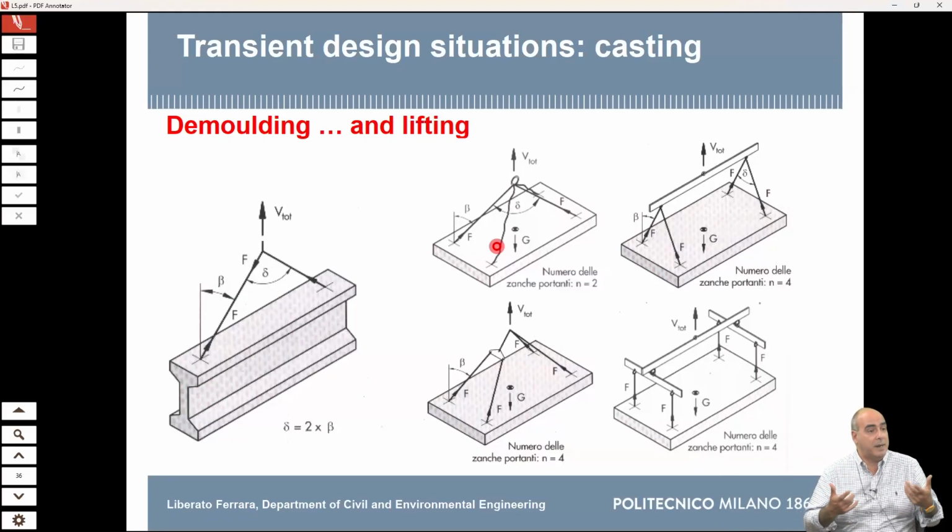But you might have premature cracking. If your element starts cracking and the crack width is already too wide, already in this stage, you will never recover it. And you can have some deformation, and consider that if it's cracked, then there is the interaction with creep. You can have your element going into service, which is already some permanent sagging.